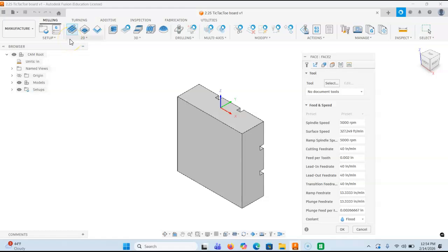It's very critical, and not just for cosmetic reasons, but for establishing an accurate starting point for all of our Z depths. In CNC machining, if the top surface is uneven or tilted, it can mess up all future features, and it can certainly affect how we're holding the part for future operations as well. So bear that in mind.